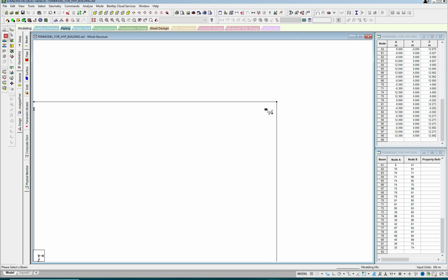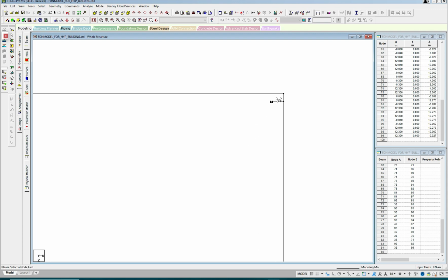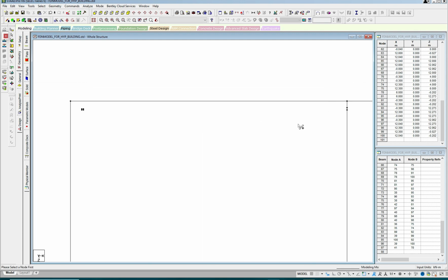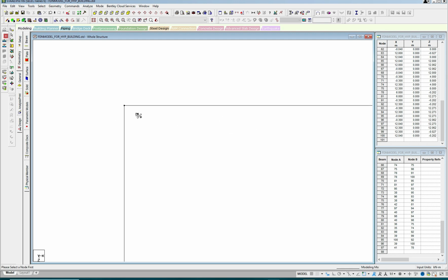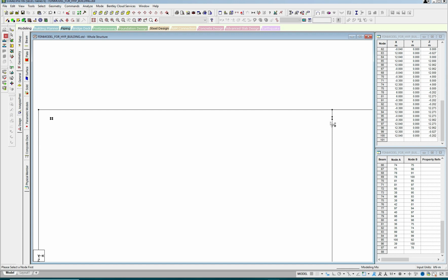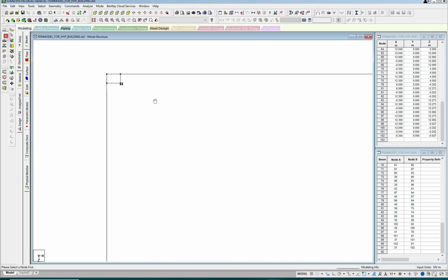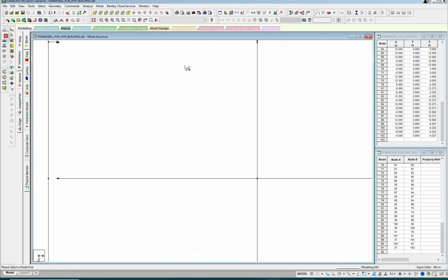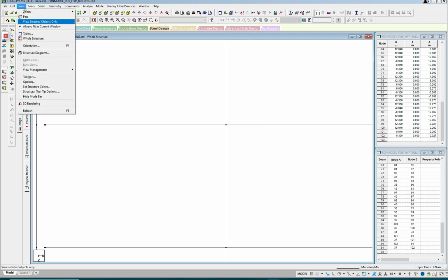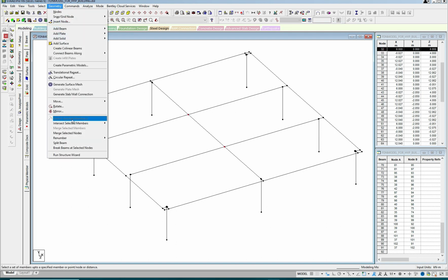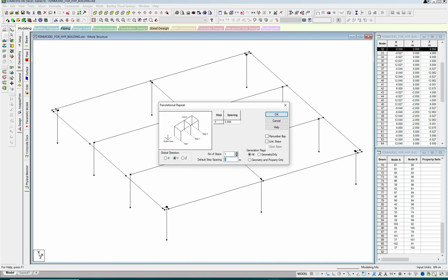And here again, perpendicular from pedestal center. Here you join the pedestal center, then here you draw perpendicular on the pedestal center. So, view whole structure. We have some pedestal here also. Their centers match. So geometry, translation repeat, y minus 2.05, link step.